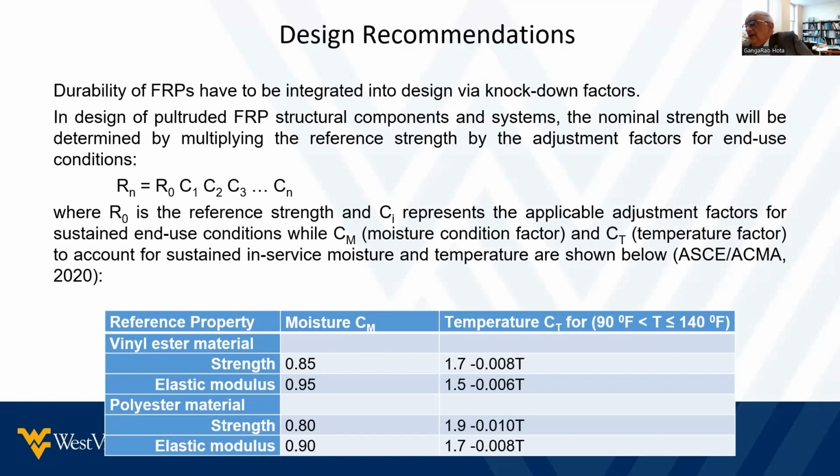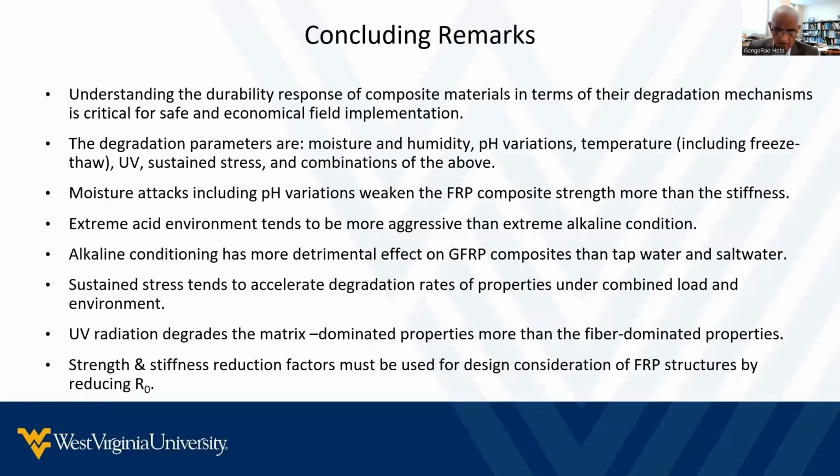One is strength-based fatigue degradation factors. The second is the stiffness-based fatigue degradation factors. Obviously, the strength degradation factors are more severe than the stiffness factors in all loading scenarios except shear. That needs to be highlighted.